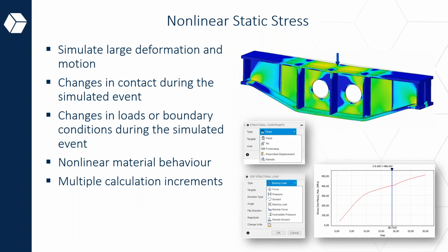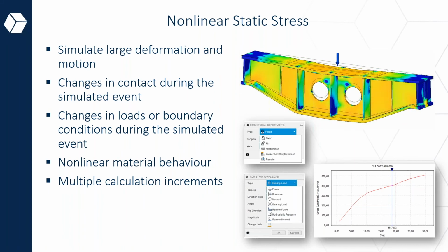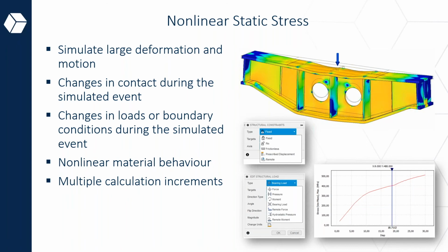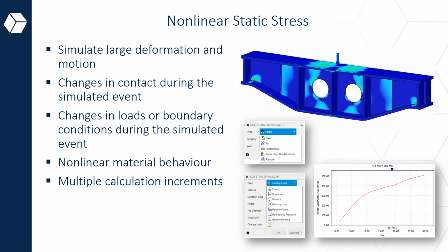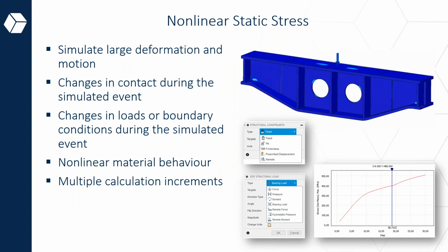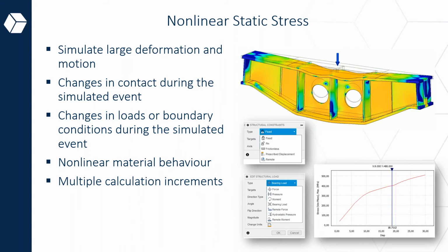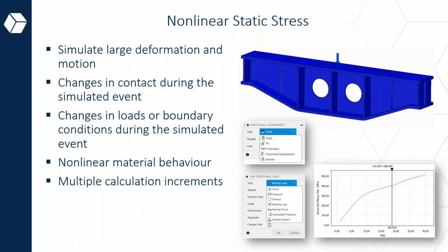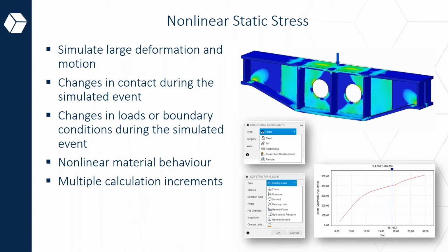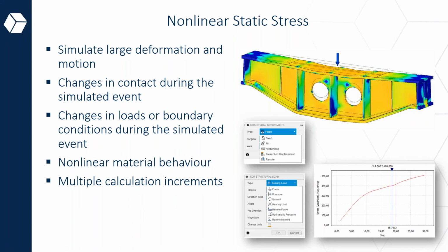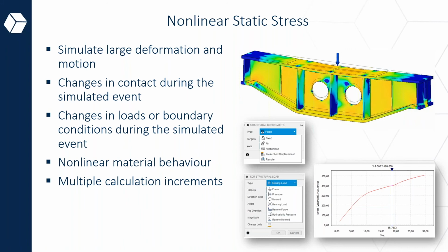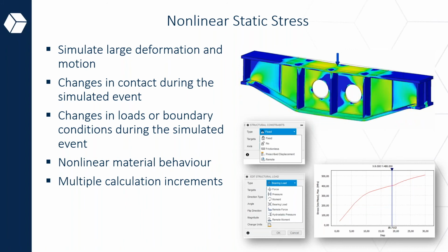larger loads being applied. The way in which this works is that when you apply a load, your part deforms, and when the deformation happens, the load and the stresses as a result of the load are changed due to the way the contacts are changing, due to the way the boundaries are changing, and how all of that interacts with each other. That's what this simulation is taking into account and showing you. This is a really realistic way of doing a simulation.